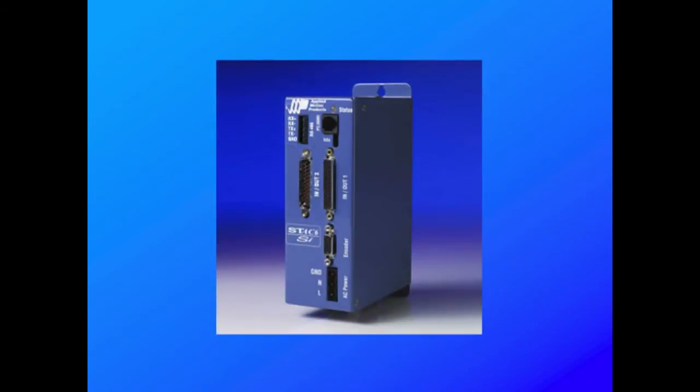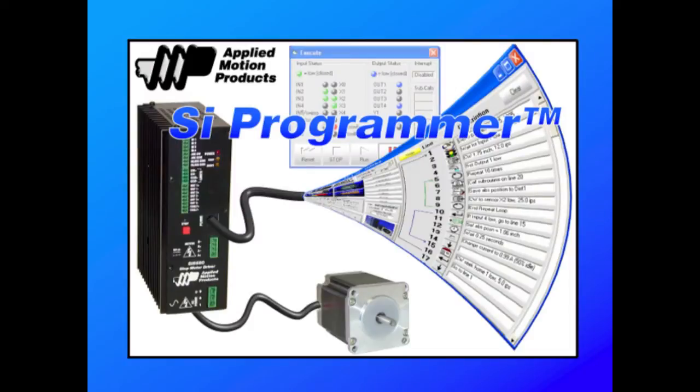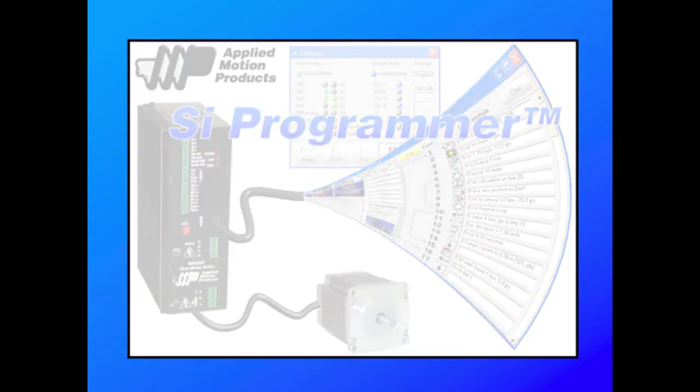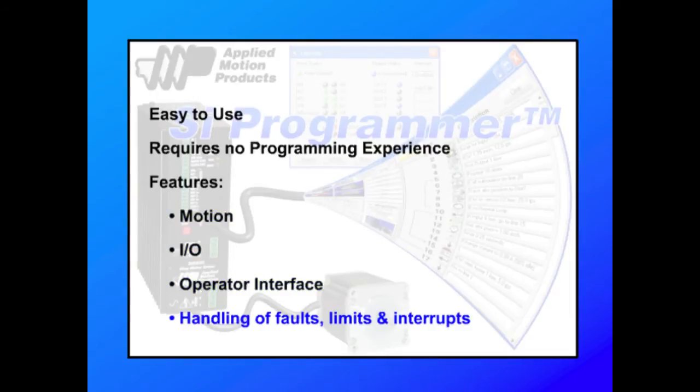The Stack 6 SI works with our popular SI Programmer software for creating programs to be stored in and executed by the drive. The SI Programmer is easy to use, requiring no previous programming experience. You can quickly and easily create programs which include motion, I/O, an optional operator terminal, and the handling of special circumstances like user interrupts, drive faults, end of travel limits, or motor stalls.